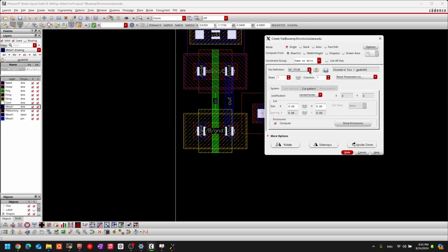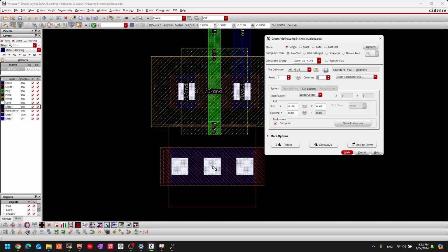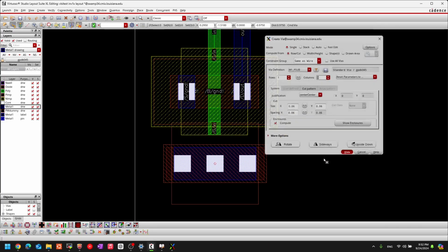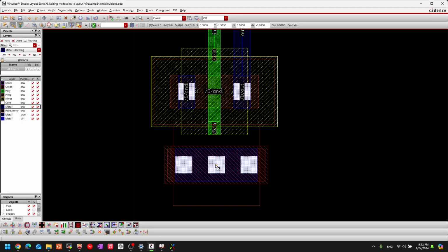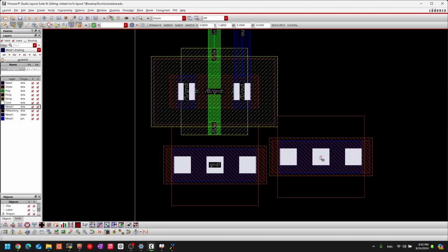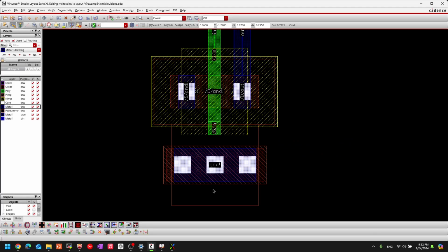And this is where you connect the ground to the source terminal. So we got the P-sub. Let's do 3 for this as well, and insert it somewhere in the middle as well. So got it here, here, maybe here. Doesn't have to be specifically in the middle.